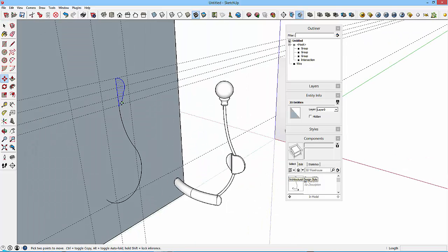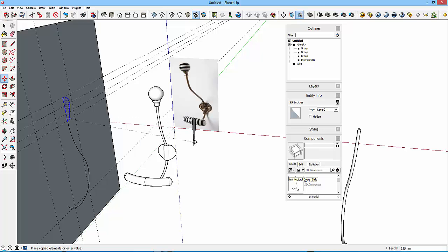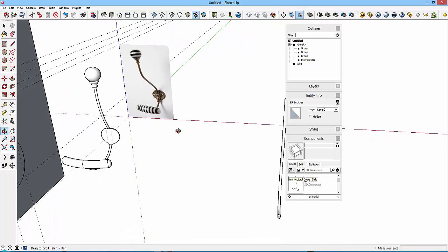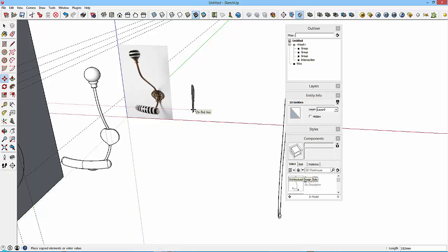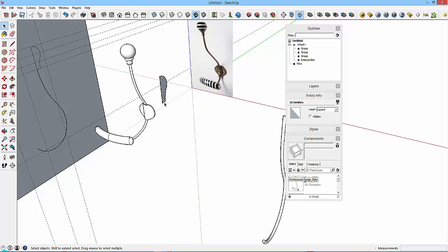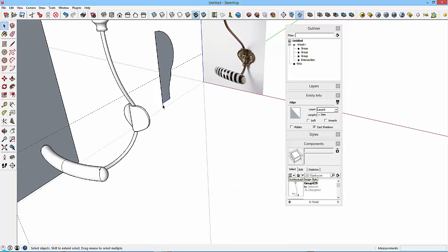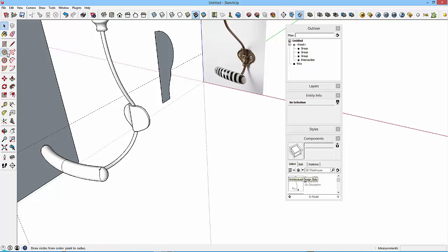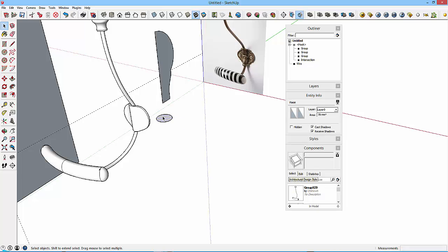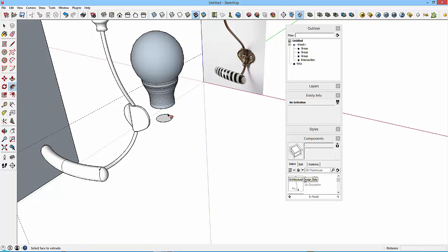So I'm going to copy this on the red axis again. The last one was 500mm. If I go, say, 300, don't know where that disappeared to, and just get rid of that little bit there, and then use the circle tool and hover over nothing, so I'll put it on the floor as it were, and shift key to lock out. Don't click at this point, you just want to track down from that point on the blue axis and then just make any size circle. This is our path defined by the face, and we're now going to click on that to create that.